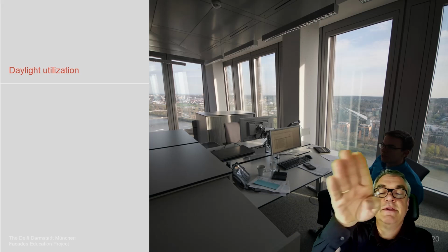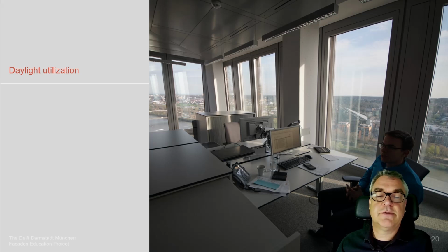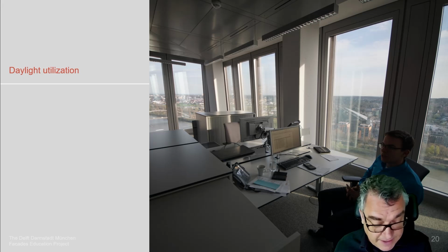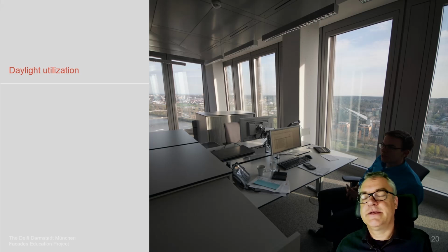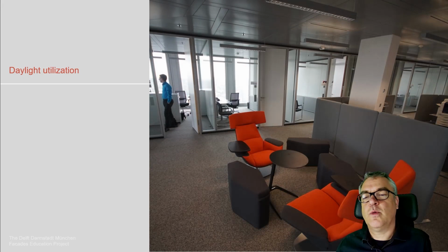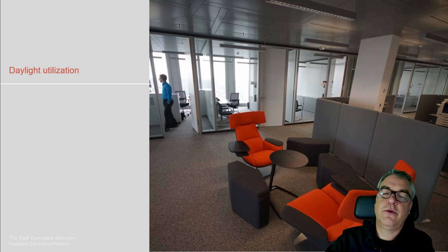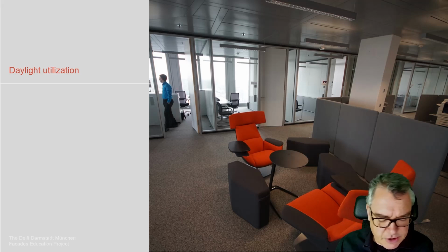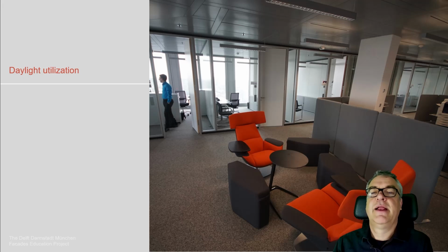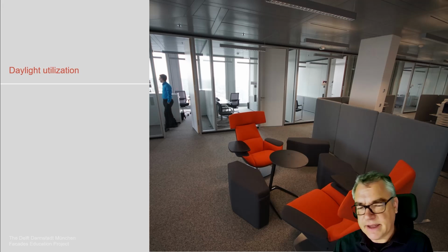The surfaces here, the inner surfaces, are designed so that there's enough reflection of the light as well. 500 lux, something like this, at this inner surface, while in the inner part, in the corridor part, for example, there's no working space, so the illumination could be less, so it's allowed to have less light there. And then again, if it's too little, then you start using artificial light.